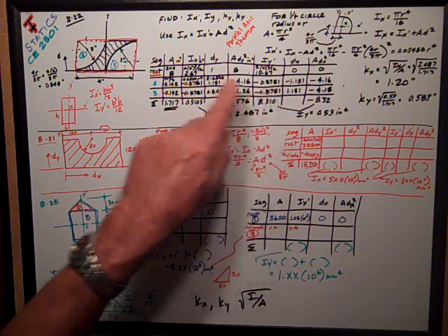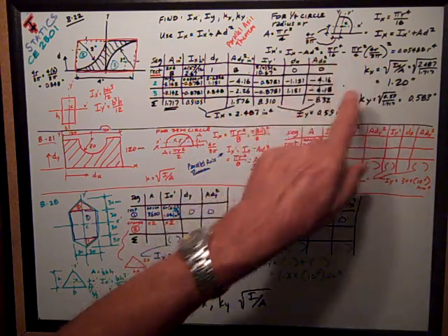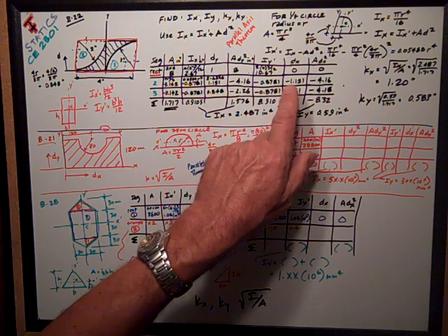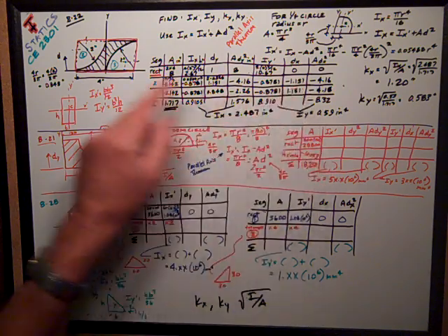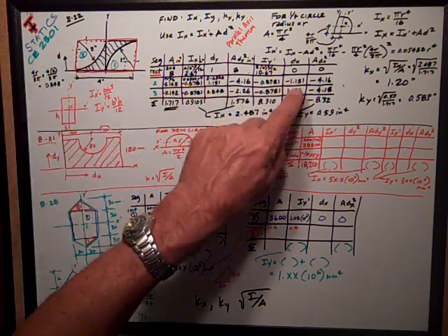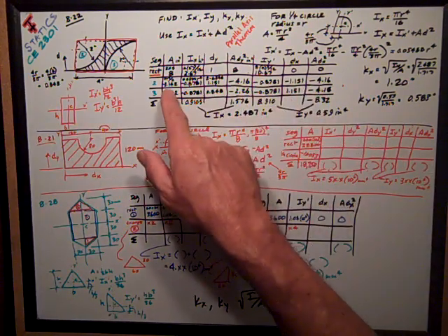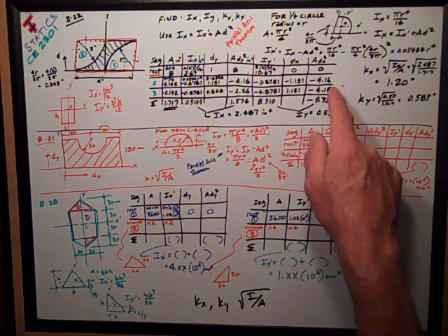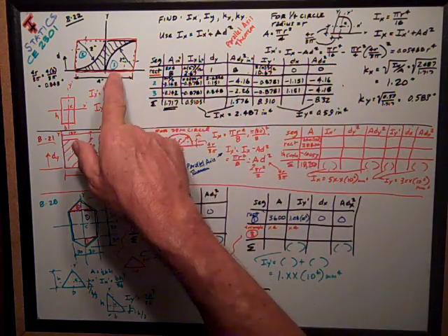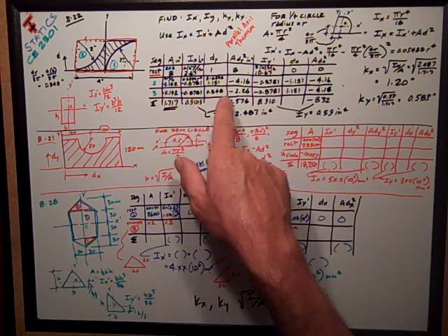Iy is similar, but look at it. Its moment of inertia about the y-axis is the same as the one about the x-axis. It's a negative 0.8781. Its dx distance to the centroid is that same thing, 2 minus 4r over 3 pi, negative 1.51. I'm going to square that, multiply it by the area way back over here, so I get a negative 4.16 for ADx squared.